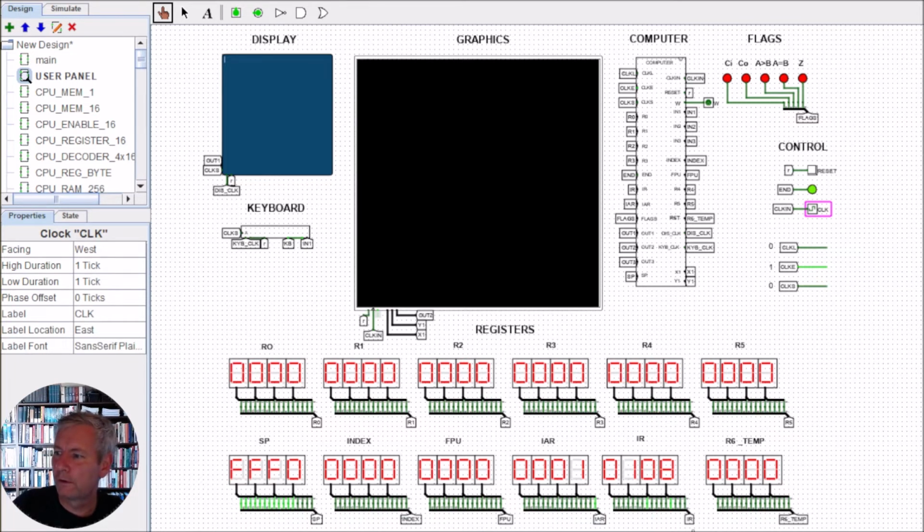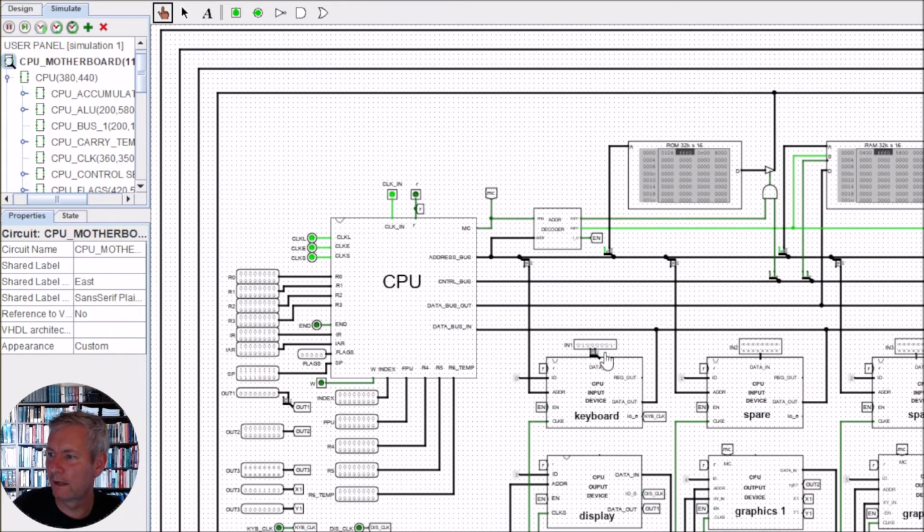So we've got the stack pointer set up, and you see here that it's now jumping. So that 0C00 is the jump to the first address of our RAM, and then it should pull in 400, and there you see it's pulled in the value 400. Okay, so that's our instruction to load the keyboard value into the register. So I'll count through a few of these and we'll go and see where we are within the actual